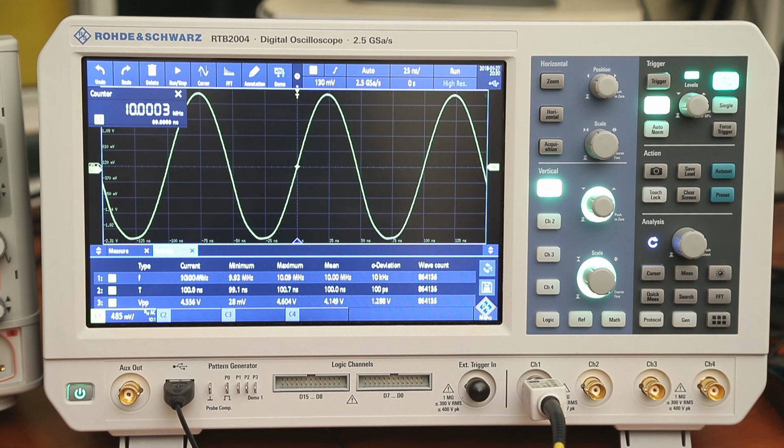And there are certain functions, like math functions, which I do still reach for the Keysight, but for normal signals I also think the 10-bit ADC on the RTB, having now had it for 7-8 months, is far superior to the 8-bit on the Keysight. Sometimes it doesn't matter, but there are certain waveforms where it does matter, particularly if you're looking at noise signals or power supply. I've been doing some work with FPGAs recently, and looking at analog power supplies and buck converters, and I just find that the 10-bit ADC does give a better, clearer signal and shows more detail. There are advantages to the Keysight.